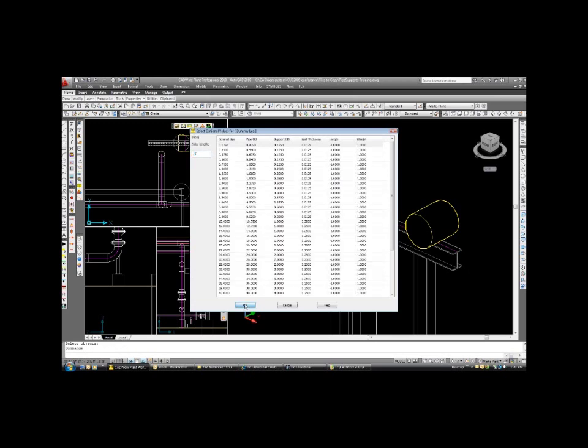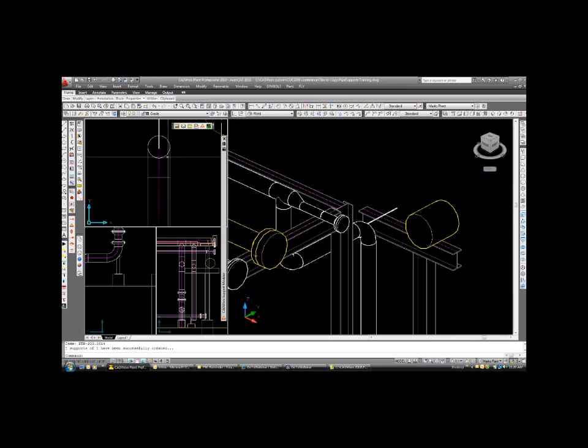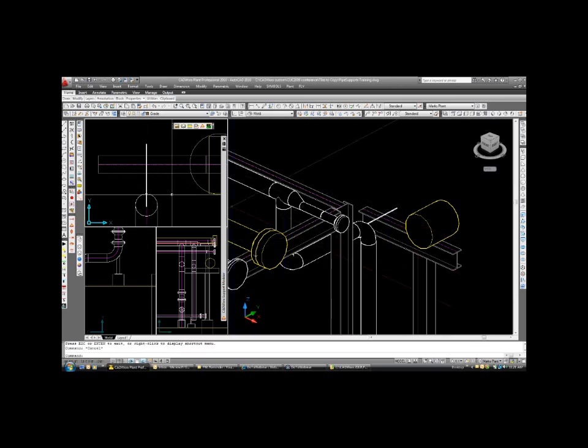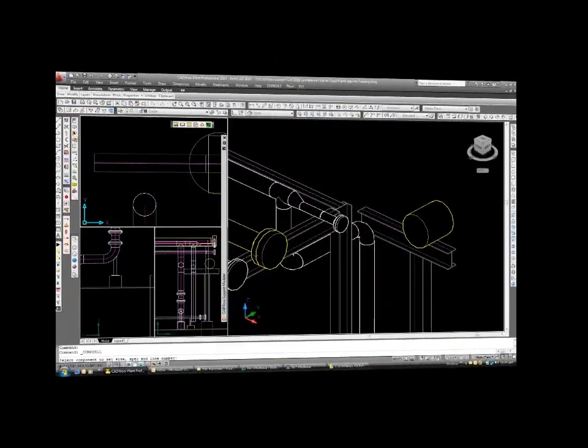And select. We'll come out over to here, put it in. Now you'll notice that the dummy leg, and I did this on purpose, that this dummy leg itself is awful thin. The reason being is because in the pipe support file that we selected, it's got a 1-inch diameter on it. Well, you know, we really didn't want to do that. So let's see if we can go over here.